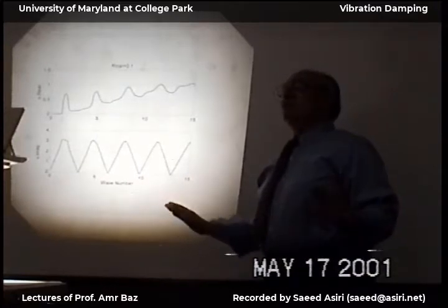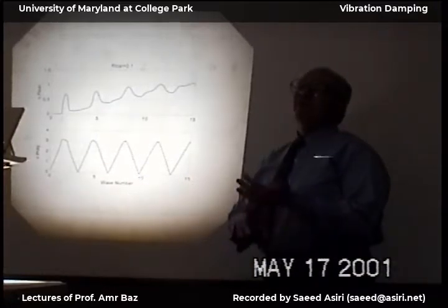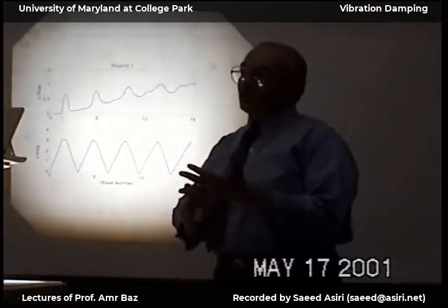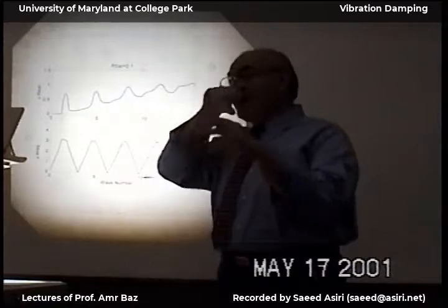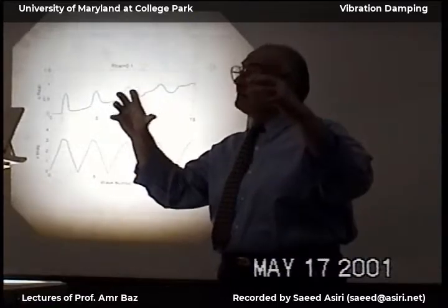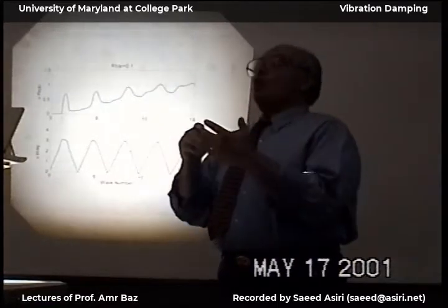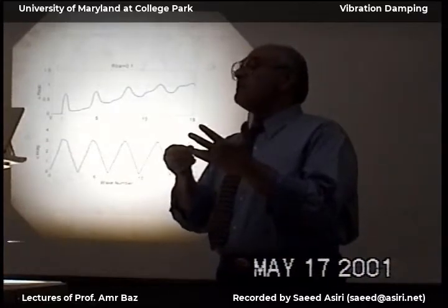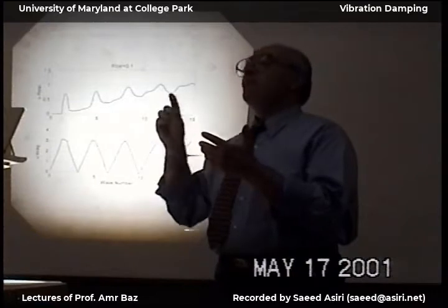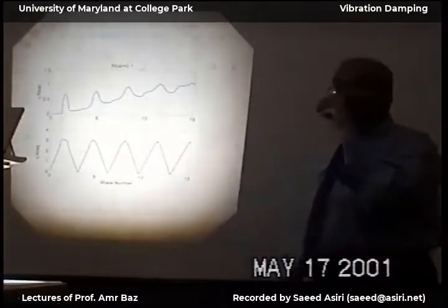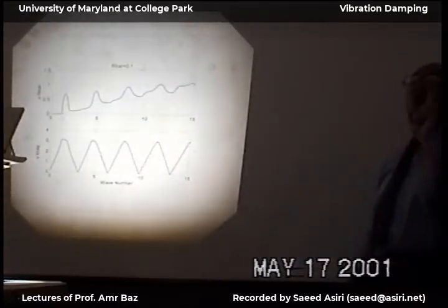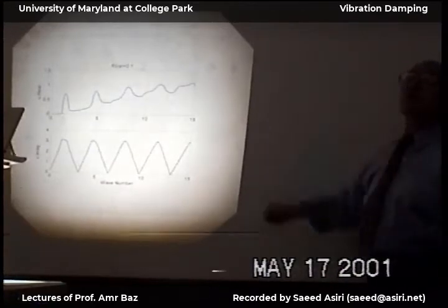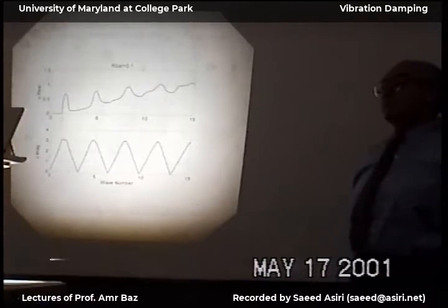So we've done a fantastic job in periodic structure. We gave you periodic alone, with no passive. Aperiodic, when you introduce any randomness in how you assemble the system. And we looked at frequency response, time response, and then localization. Then last lecture we did rods. So you can look at spectral finite element and then how to assemble this with shunted piezoelectric material.